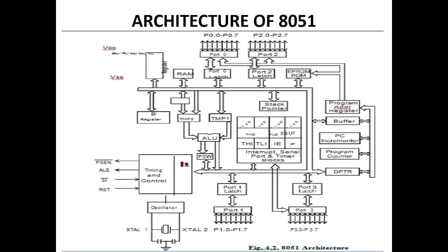And then finally, the oscillator. The 8051 generates the clock pulses by which all internal operations are synchronized. Pins XTAL1 and XTAL2 are provided for connecting a resonant network to form an oscillator. To form this clock frequency, a quartz crystal is used for the oscillator. The crystal frequency is the basic internal clock frequency of the microcontroller.